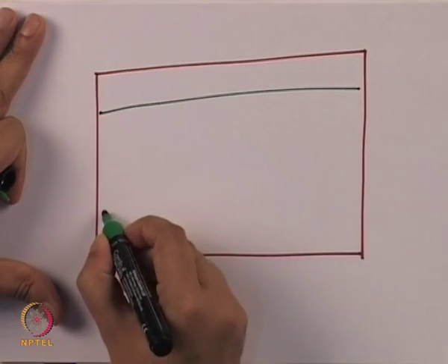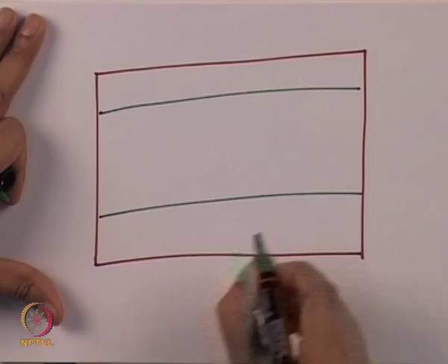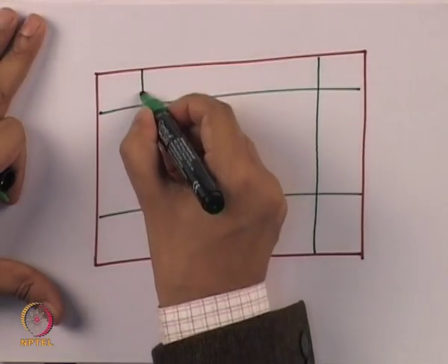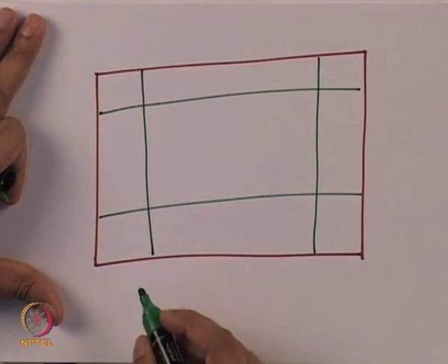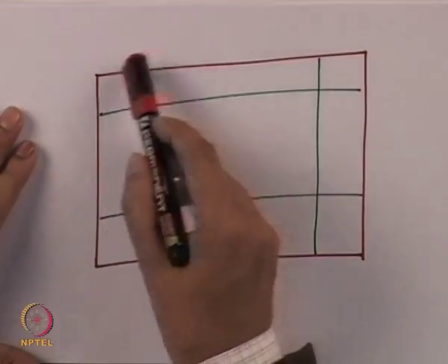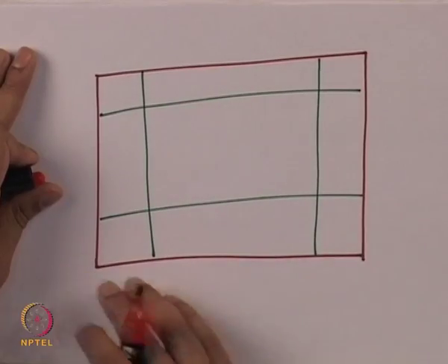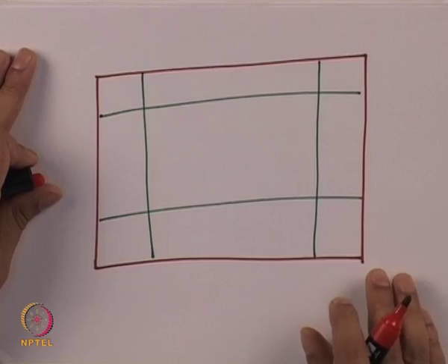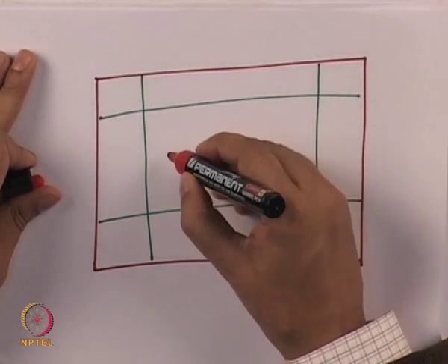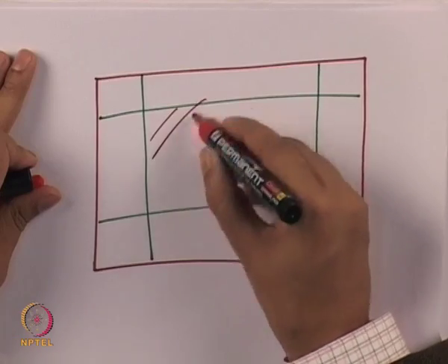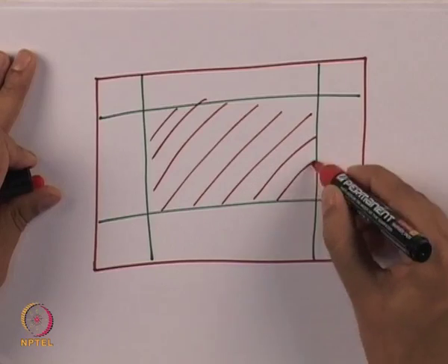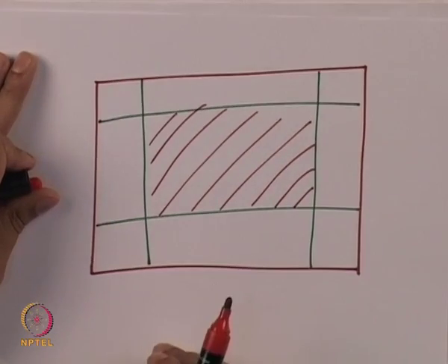You will have top and bottom PML, you will have the right and left PML. As you can see, the real computational domain is going to be the entire domain. Although the entire domain is called the computational domain, the object of simulation will be mostly sitting in this area. So we will be keeping all the objects that we are modeling in this area,